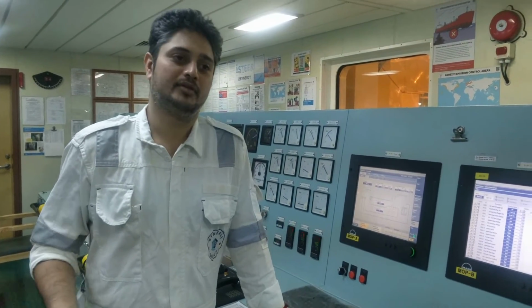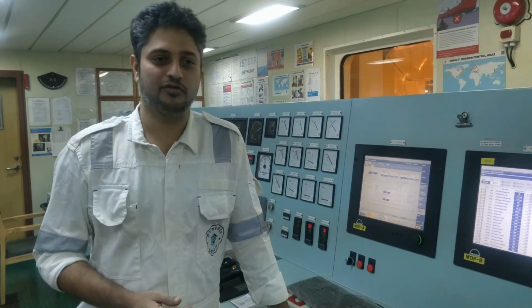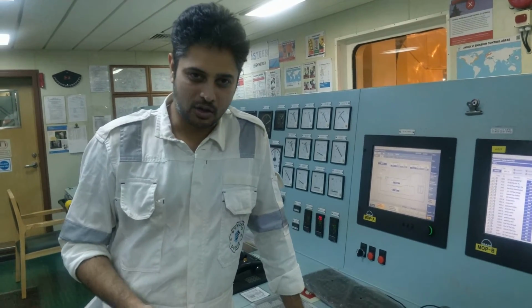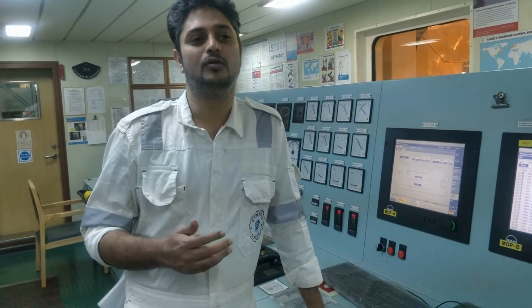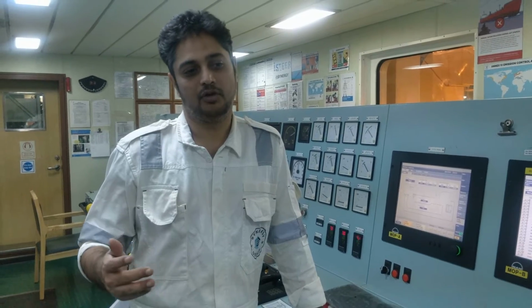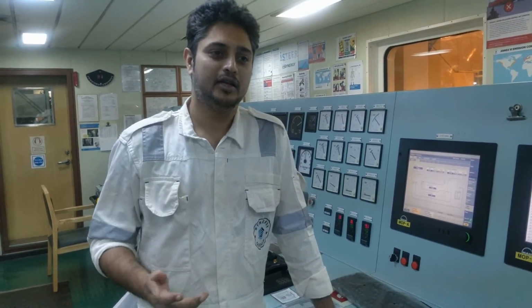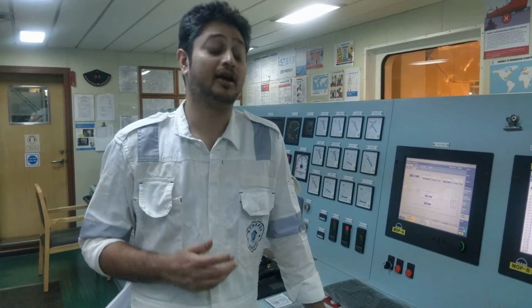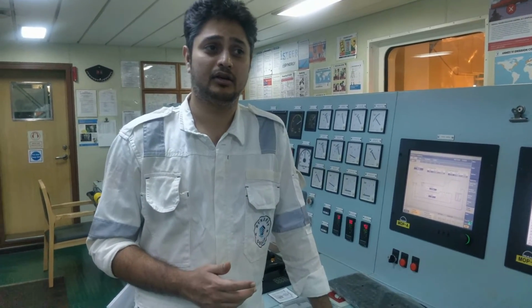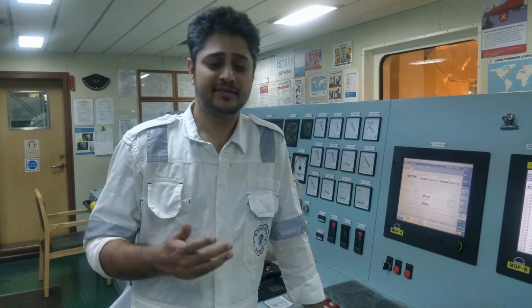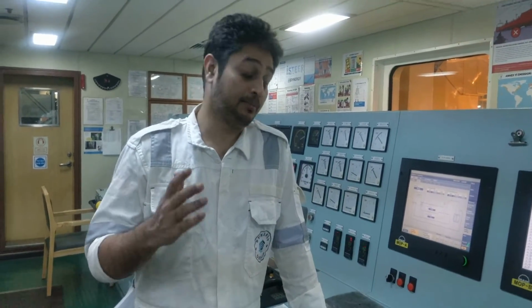It involves, depending on the problem which you face, whether you want to cut out only the fuel or whether you want to cut out the exhaust valve from operating. It depends on the issues you face, and accordingly you have to take a decision. For cutting off the cylinder for prolonged running, it is better to ask the makers how much load I can run the engine on a prolonged basis.